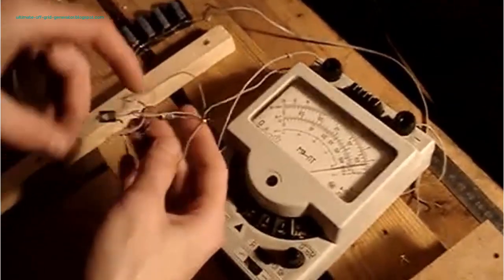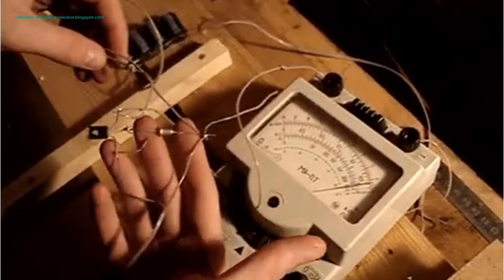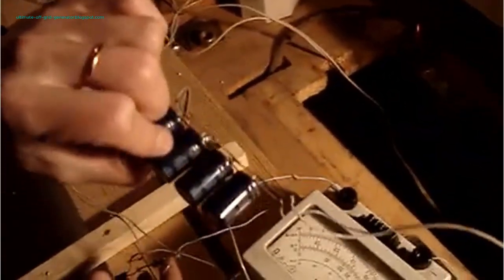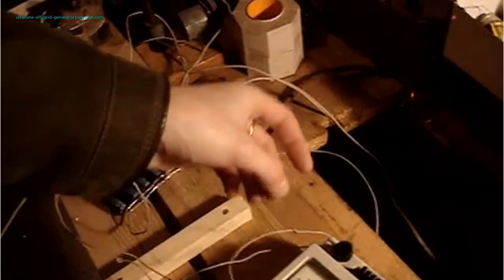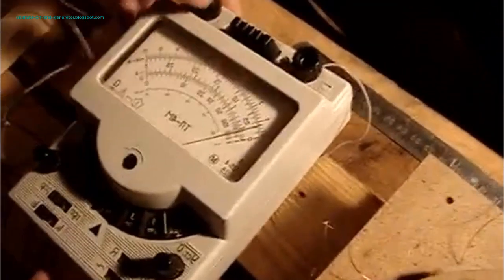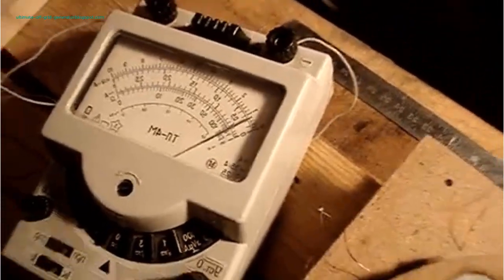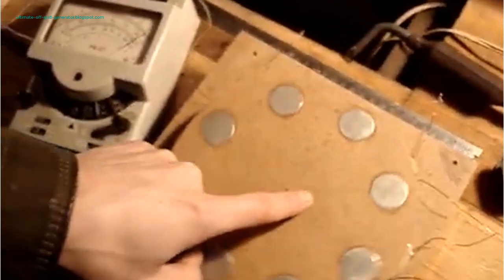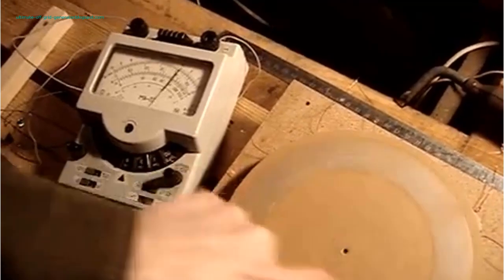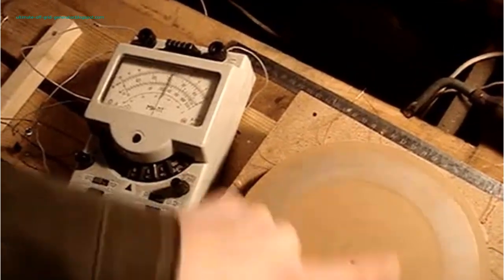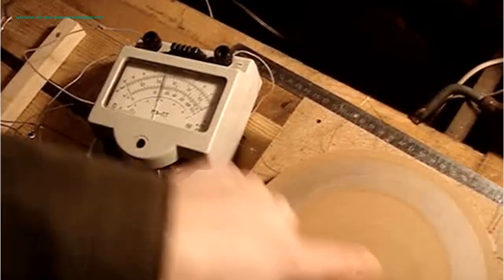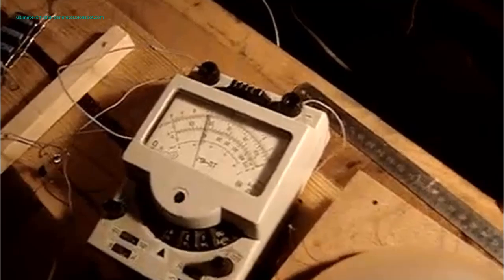At this point, something special occurs, something rarely discussed. The iron core becomes fully magnetized, and the magnetic flux through the core stops changing. The magnetic field of the core collapses exactly when the magnet crosses the center. This creates a reverse EMF. At that moment, the voltage at the transistor's emitter suddenly becomes much higher, making the base voltage relatively lower. As a result, the transistor switches on. Thus, both the Hall IC and the NPN transistor unlock at the precise moment the magnet crosses the center.